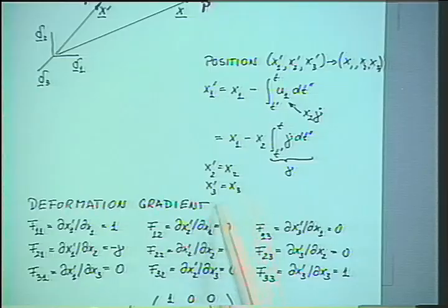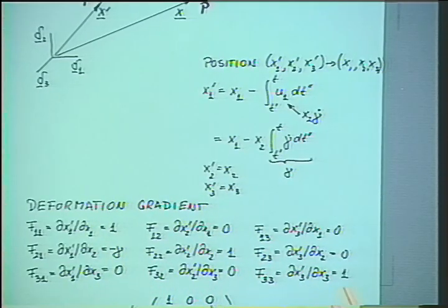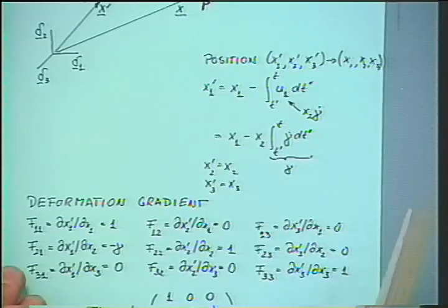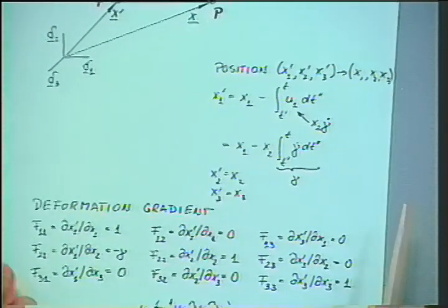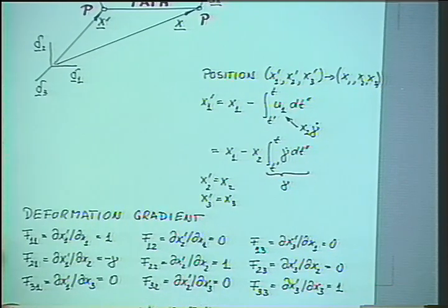And in the three direction here, a similar component. Those are the stretching components, which don't amount to anything. We know that there's no stretching. And these components then result in a deformation gradient, which we have here. Okay, this is the deformation gradient.